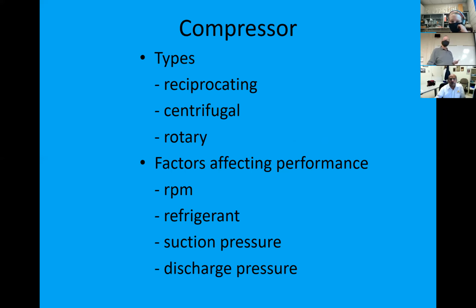Some of the factors that will affect performance here, and what you would need to think about when you're deciding which one of those to use: the revolutions per minute, what refrigerant we are using, the suction pressure, how much suction pressure do we need, and what is the discharge pressure that is being generated. Again, all of this may be things you just file away so that you can talk smart, or listen smart, when you're talking with your refrigeration engineer.